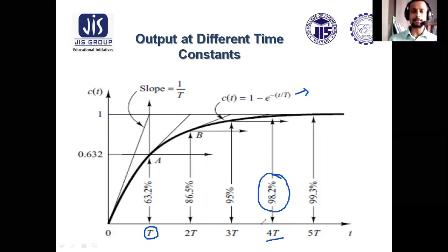So 4τ time is known as settling time, the time taken by the response curve to get settled down to a steady value. For 5% basis calculation, 3τ time is taken as settling time. If much accuracy is not needed for a particular system, in that case we can consider 5% basis calculation. In 5% basis calculation, we could say a system is at steady state or system output is settled down if the system reaches 95% of its final value. So settling time for 2% basis calculation would be 4τ. Settling time for 5% basis calculation will be 3τ.